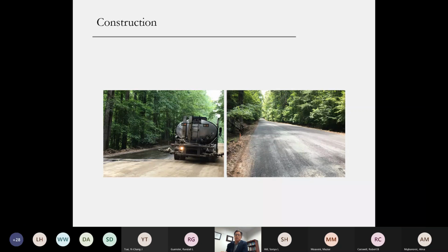And before you place the asphalt concrete, in the state of Georgia, we use chip seal layers. The chip seal layer provides a temporary driving surface, but is also designed to serve as a bond breaker, because the cement treated base will be prone to shrinkage cracks, and without the bond breaker, those shrinkage cracks would reflect to the finished asphalt concrete sections. To avoid this reflective cracking, we use the chip seal layer. This is common in the state of Georgia and also South Carolina.